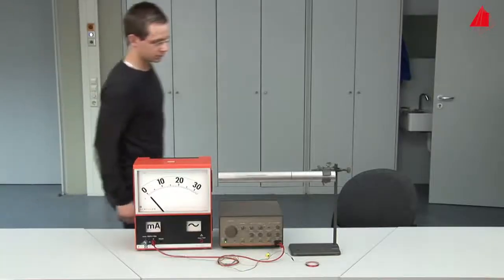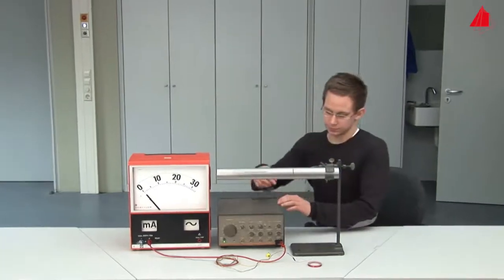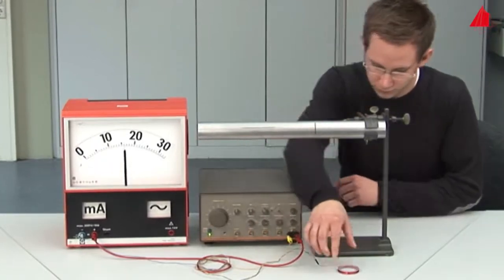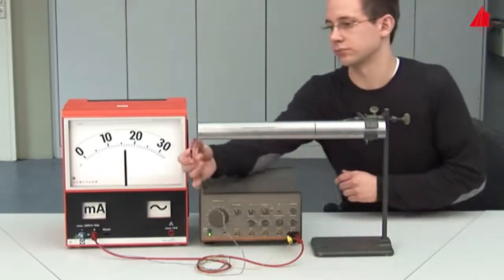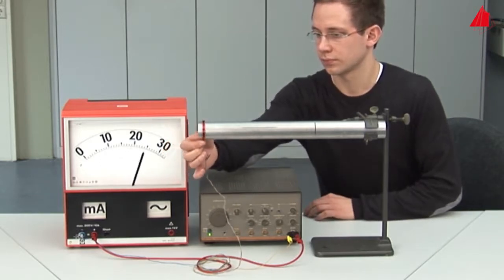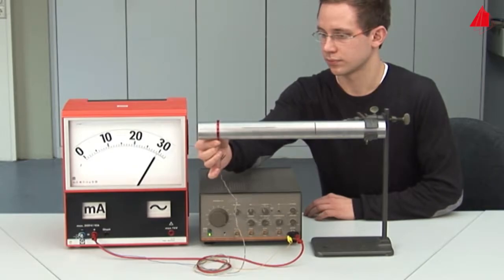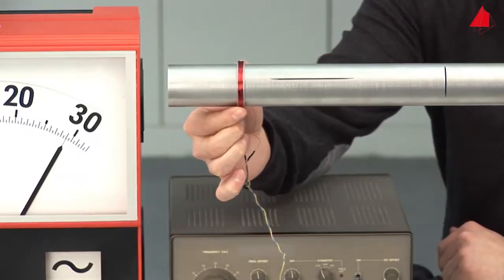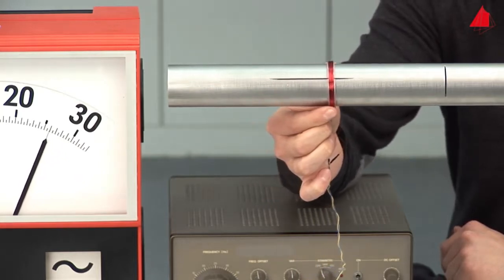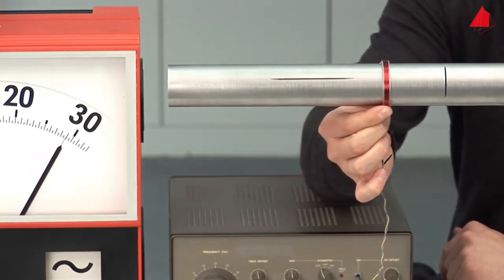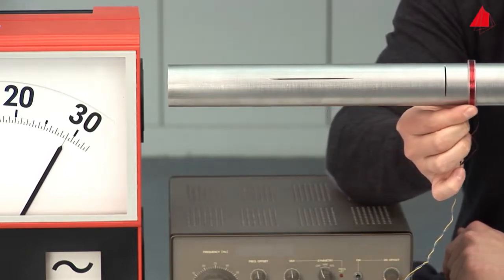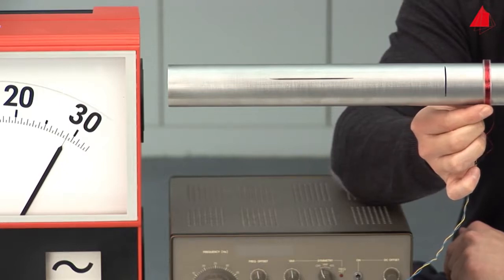And here we go. The materials tester connects the return cable to the alternating voltage source. This closes the electrical circuit. The current consumption of the coil is still relatively low. Once the coil is positioned over the intact part of the tube, the magnitude of the current is high. The current decreases in the region of the longitudinal cut and reaches the original magnitude again in the intact part of the tube. The cut in circumferential direction has apparently no influence on the current.